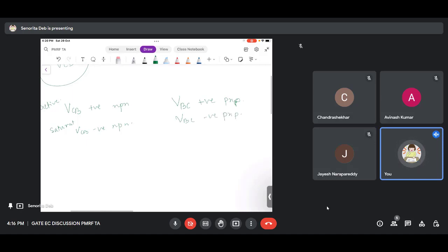And if you have any doubt in remembering this, then the way I did it, you just draw the transistor. You know it is NPN. So positive of diode here, negative here, positive here, negative here, and now C is here, B is here. So if I put a positive VCB, this diode is reverse bias. So here it is reverse bias. If I put a positive VBE, this diode is forward bias. So input forward, output reverse. This is in active region. So therefore I know for NPN, VCB positive will be active region.